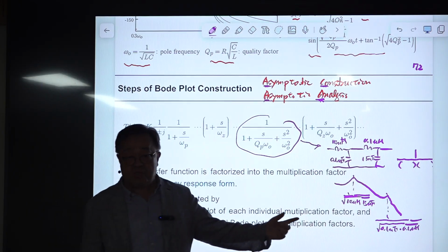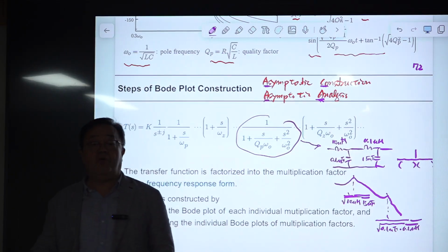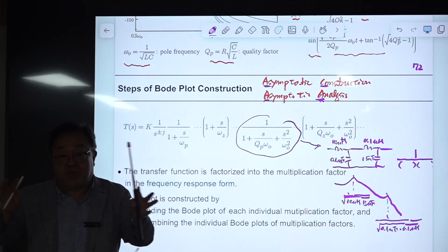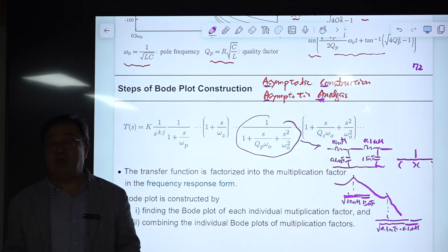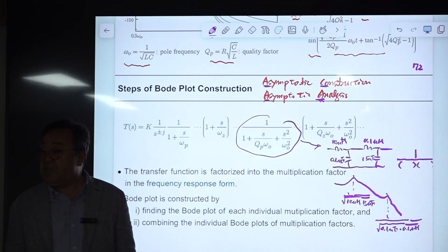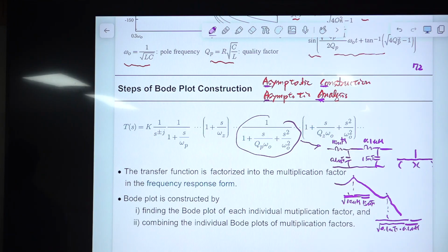When you are doing this, use the component values wisely, so later on you can easily analyze this. If you put everything together, you cannot do anything. Maybe a PSpice simulation or some simulation is available, but that is just garbage. It does not provide any insight for design improvement or for control design. Okay, so this is the engineering approach. It is called design-oriented analysis.